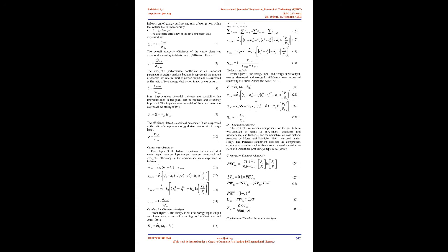Increasing the high-pressure turbine, HPT, inlet temperature at constant boiler pressure increases the component's exergy efficiency as well as the power plant's second law efficiency, reducing the component's exergy destruction. Oswick et al., 2015, conducted an energy and exergy analysis for the various components of the Sapele steam power plant. According to their findings, the boiler contributes the most energy loss, with 105 kilowatts lost to the environment and only 15.7 kilowatts lost from the condenser system.